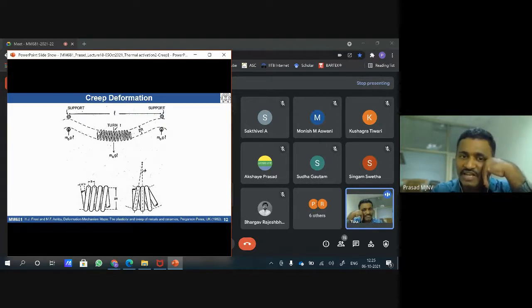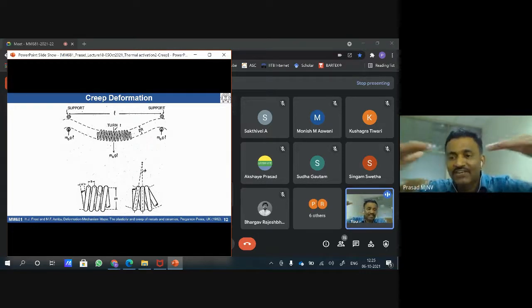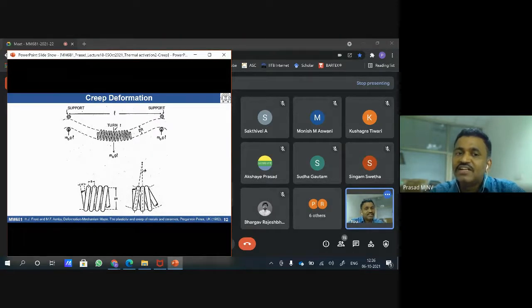So typically we have these turns because of plastic deformation under high temperature and self weight. It is going to extend slowly, so that leads to increased strain, and the length of the wire is going to increase. After a certain number of hours, we are going to see these touch each other, which leads to sudden fuse out.